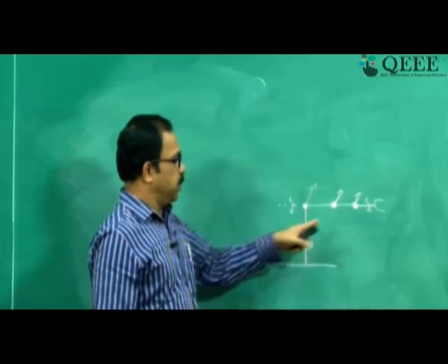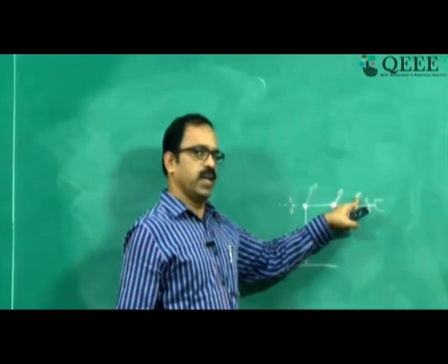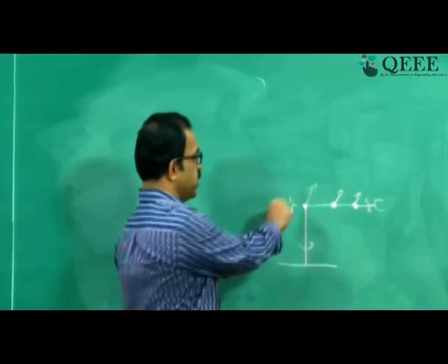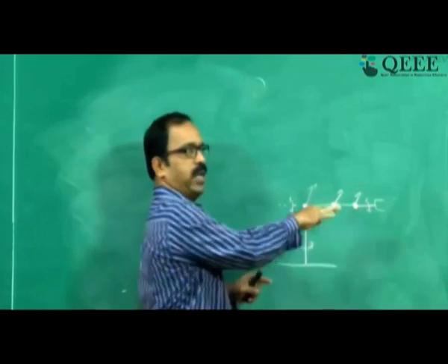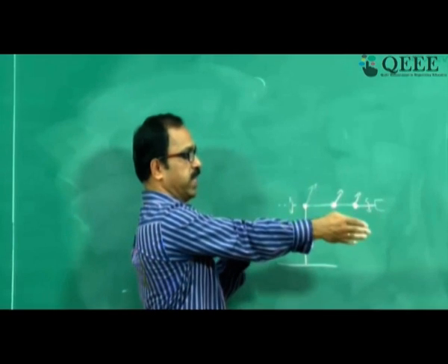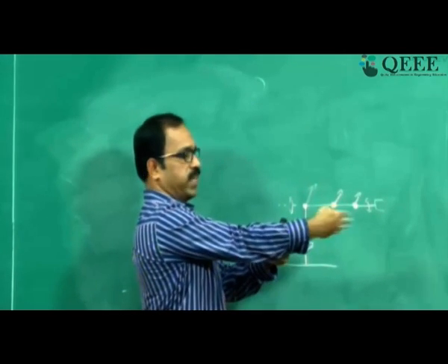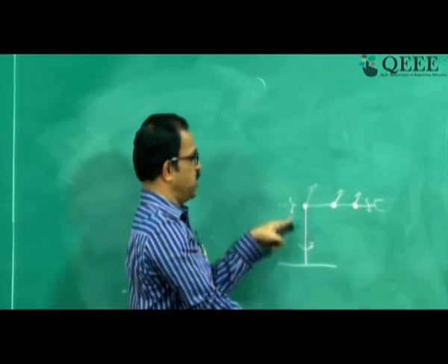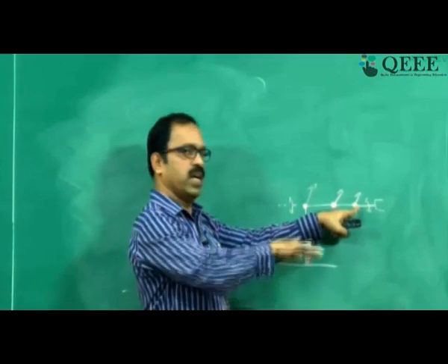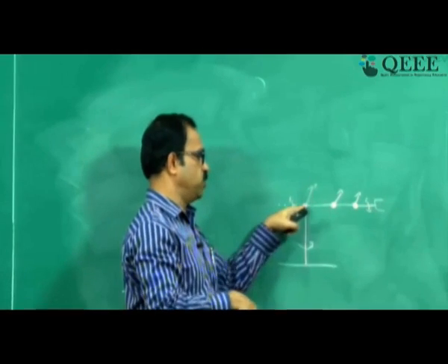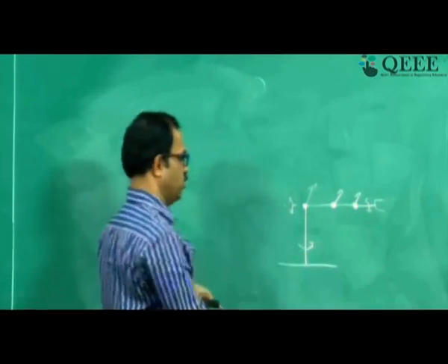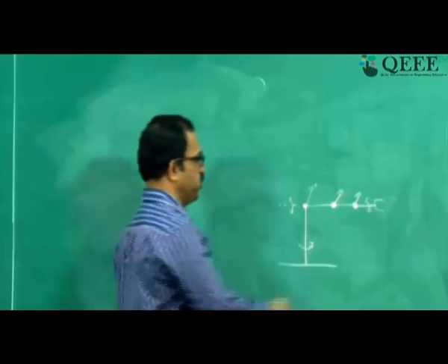So you can see that the pitch axis is here and the yaw axis is actually missing, but if you rotate this by 90 degrees, this pitch will become a yaw axis, because if I rotate this axis here, it will become like this. So that is what this joint helps us to get: another rotation, by rotating this by 90 degrees, the pitch axis can actually convert into a yaw axis also. So that is the configuration of this manipulator.